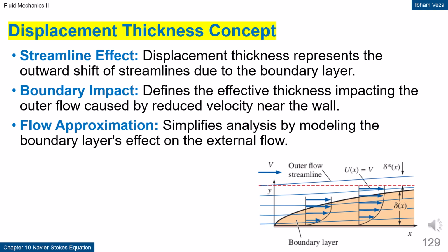The outer flow feels this effect as if the body's surface were thicker. This concept allows the effect of the boundary layer to be incorporated into an ideal outer flow analysis. In this way, the interaction between viscous and inviscid flows can be modeled in a simple manner.